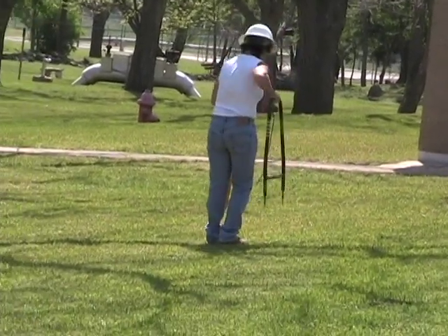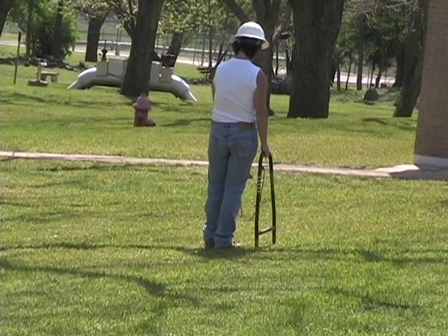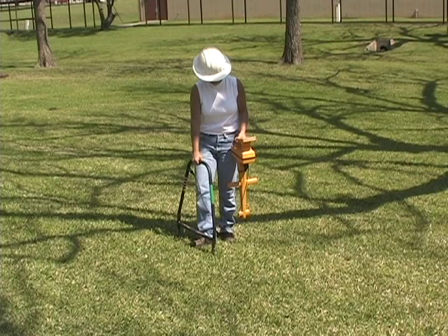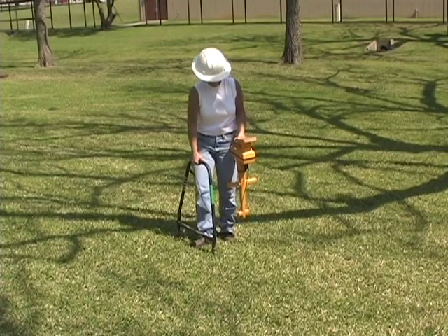Probe the ground back and forth until the fault is centered between the red and green legs of the A-frame. You have now located the fault two-dimensionally. You have centered the A-frame over the fault in the forward and backward position. Now you need to pinpoint the fault in a left-right direction.